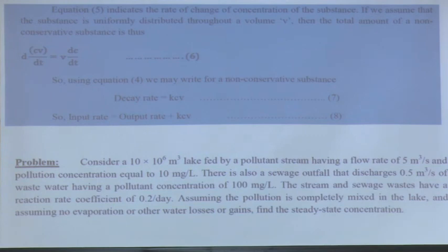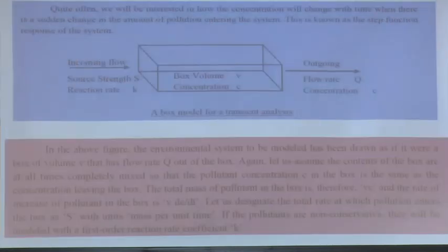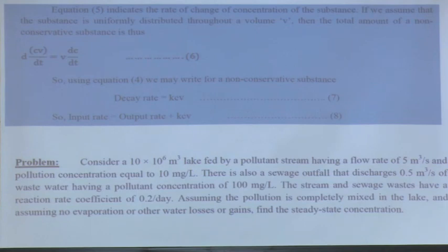So, what is the final equation? That input rate is equal to output rate plus KCV, where V is the volume, C is the concentration, and K is the rate coefficient. Now, I have not given the solution for this. I want you to solve it. Yes, I have not given the solution for that.